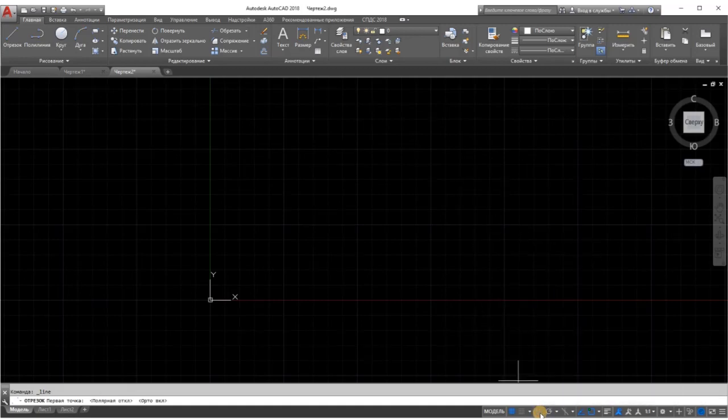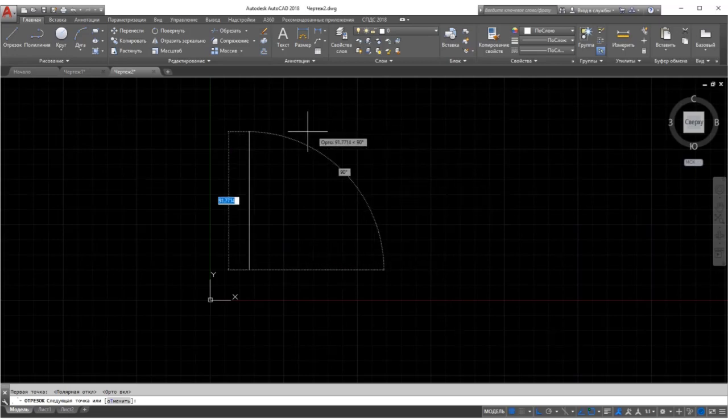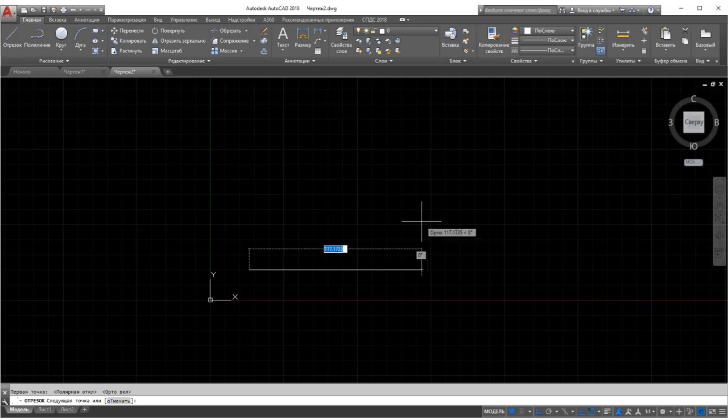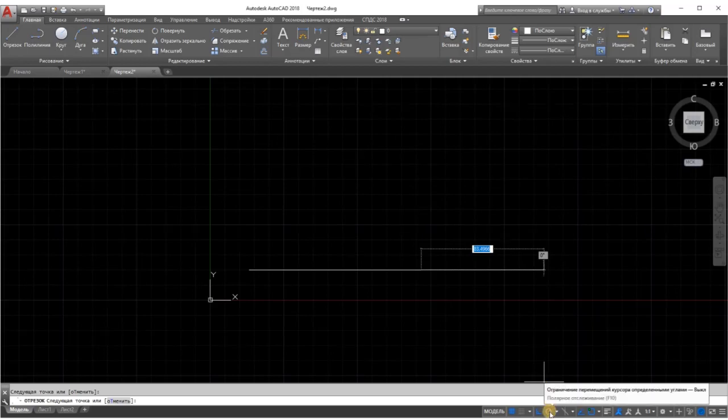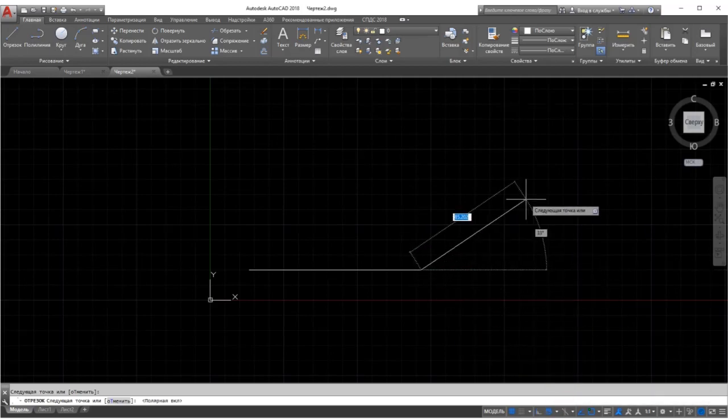If you happen to forget that a command is still active, two on-screen clues can remind you of the status of AutoCAD. If you don't see the words "Type a command" in the command window, a command is still active. Also, the cursor is a plain crosshair without the box at its intersection.